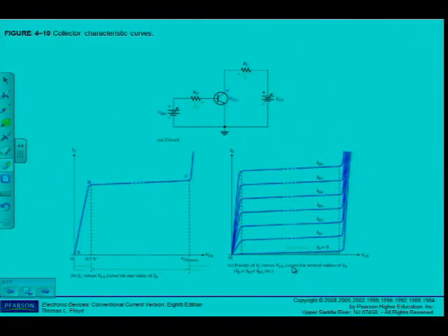Now they do it under certain conditions here, the same as we've done previously with the two voltage supplies. You will see now I still have a voltage supply on the base and I still have a voltage supply on the collector, but it's now two variable voltage supplies to be able to draw this family of curves as indicated here in figure 10.